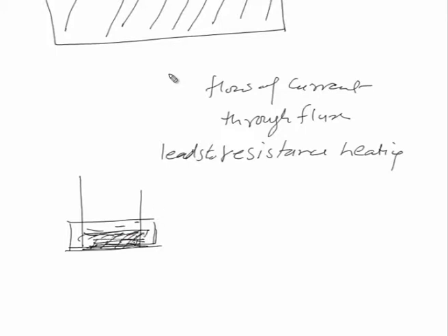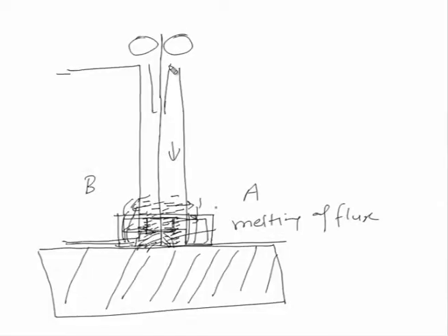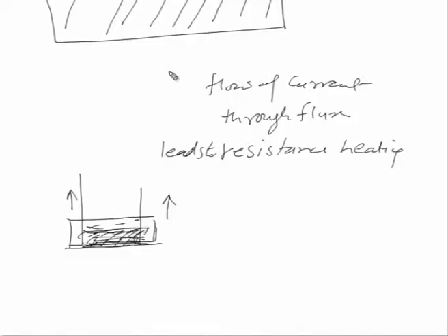Once a sufficient size of joint is made, the copper shoes keep moving up along with the electrode, and the electrode is fed downwards continuously. This continuous upward movement is done until the weld joint is made between the two plates to be joined in one go.